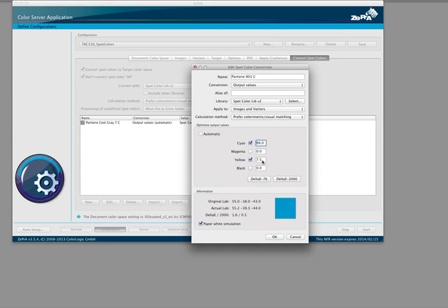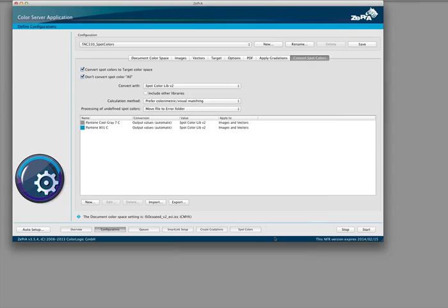And this is something which we even improve by using the automatic function, because 98% means we are rasterizing a spot color. We don't want to do that, and typically it is just 2% which is missing to not rasterize the cyan. So the automatic feature tries to get to that point and brings it to 100%. That's the reason why we have 100% cyan and 7.1% yellow, and a delta E 2000 of only 0.9, which is a very good value. So that's the way the conversion is done with ZePrA.